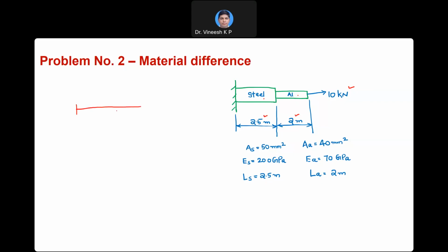So what we are going to do in Abaqus is model the entire geometry, which is now 4.5 meter in length. Out of this, 2.5 meter belongs to steel. So we will be using a partition technique where we will enter this ratio, the portion of steel over the total length: 2.5 meter divided by 4.5 meter, which is approximately equal to 0.555. Depending on that, we will make a geometry in Abaqus, then we will partition it. That is what we are going to learn in this class.